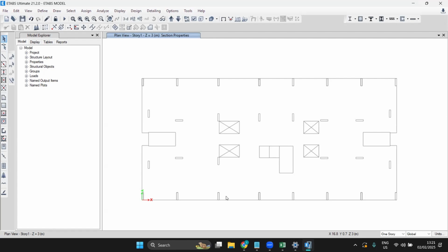Then what you do, I'll tell you. Architectural grid, and DXF file of floor plan. I first took the grid. Not this one, the DXF file of floor plan. Because you were just taking the reference plan, it does not work. Architectural grid and architectural plan are reference plans which you cannot edit. It shows only the standard photos or renders. If you want to do something, you have to take it in floor plan. Then it becomes editable.